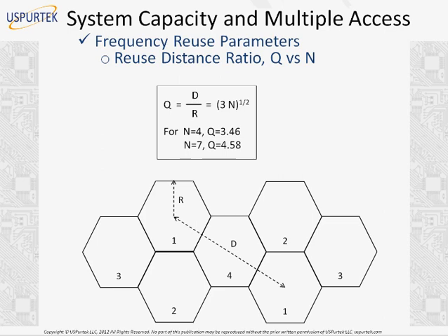Okay. So if n is very large, of course, the benefit I have is that the two cell sites will be far apart. There will be almost no co-channel interference, because the two cell sites are so far apart when the frequency repeats. But the downside is that I have reduced the bandwidth that is available in one cell site. I have only 1/10 of the bandwidth now. If I had used n equals 4, then I would have 25 megahertz, so I could have served more users in my cell site. So it's really a trade-off between capacity and quality.